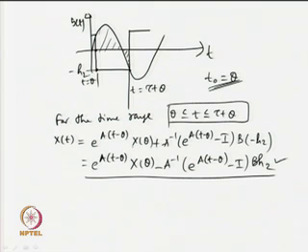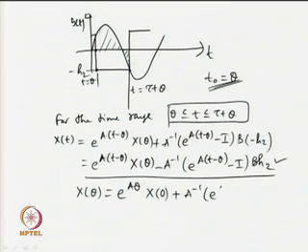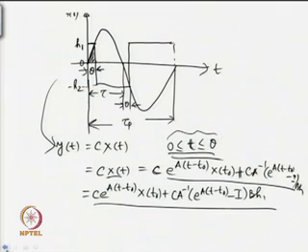But x(theta), again, we know that x(theta) is equal to e to the power A theta x(0) plus A inverse e to the power A theta minus I B h1. How do you get this one? This can easily be obtained if you substitute t equal to theta here. So, when t equal to theta is substituted over here and t0 equal to 0, one obtains x(theta) conveniently.